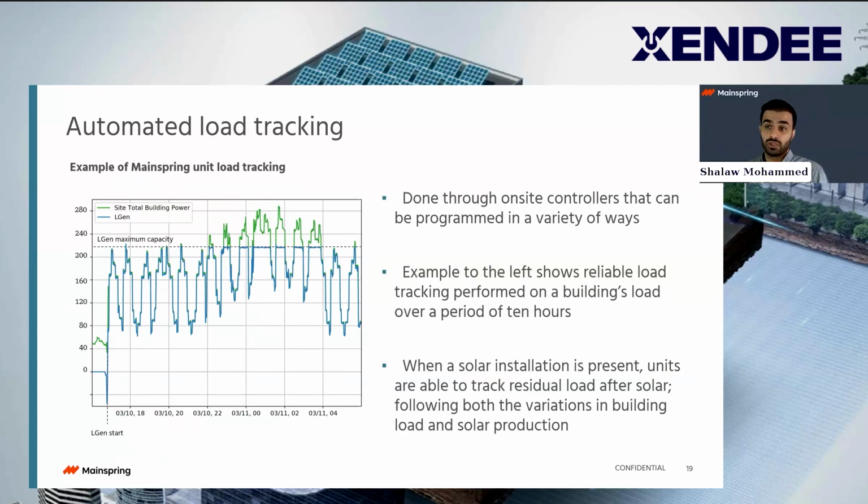So you're offsetting as much as possible from a utility point of view, then the rest will be supplemented by the utility. And this is not necessarily the case with certain other technologies, because some of them like to run in baseload. They don't like to modulate their output. Some other technologies may be just slower to respond when it comes to load. We do have batteries on our DC bus, so any major step we can take it. We can technically take 100% step load on these units without really any major disturbances that would be outside of the ISO guidelines.